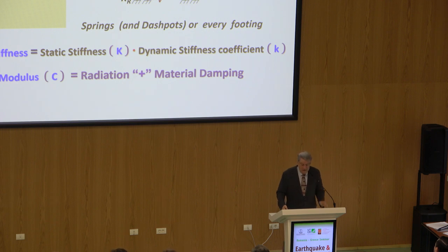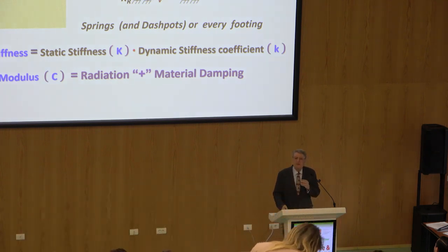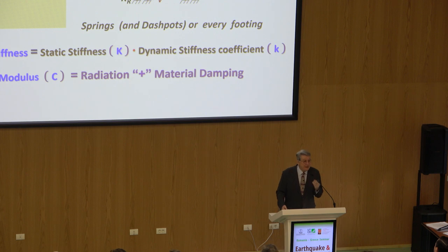things that you see there, it's not only static stiffnesses, they usually vary with frequency. And the Eurocode tries to handle this in a practical way for the engineer, other than, say, do a complete dynamic analysis, always. And the dashpots, what are they? Well, they include the usual inelastic material property dashpot, the hysteretic dashpot, as we call it, material damping, but also radiation damping.